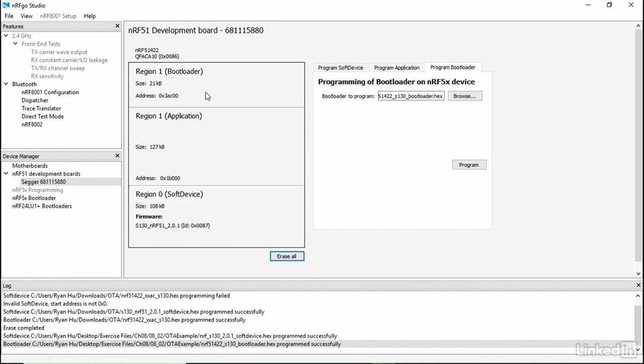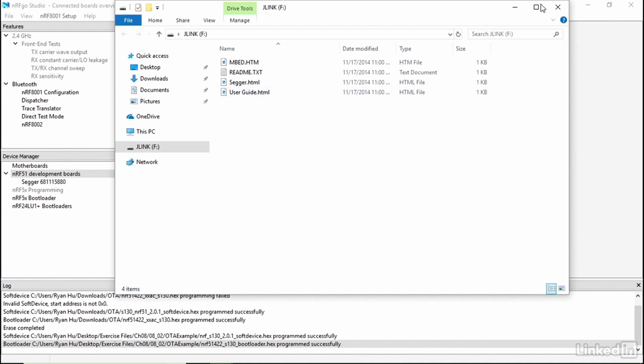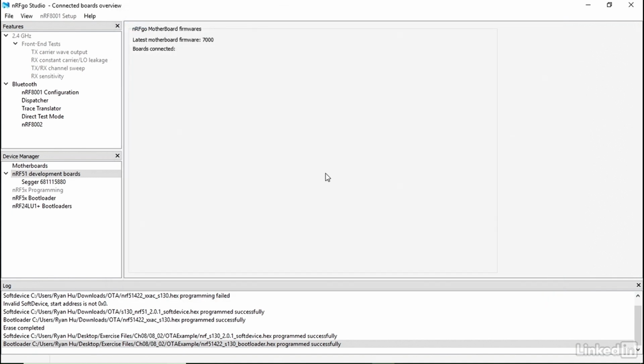Now that we have all the firmware ready for the over-the-air update, we need to make sure our Bluetooth board is in the DFU mode. To do this, we can hold the button on the board after power cycling it. Now, the last step: update the application package through the Bluetooth link wirelessly from the DFU controller.